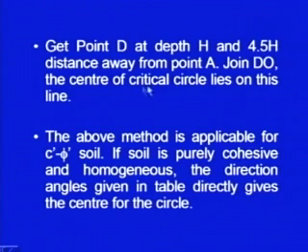It has been found that the factor of safety will be minimum somewhere on this particular line. So, we are going to take several points along this line, and then draw the contours of the variation of factor of safety, and from there you can get the minimum factor of safety. This way those tedious computations can be avoided. So, this is the rest of the procedure.